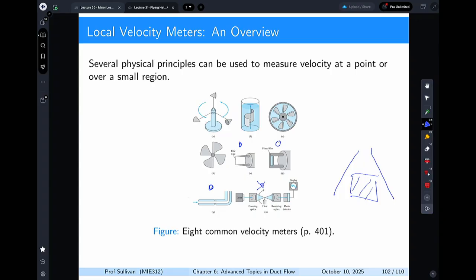The other 2 methods, and I kind of threw that one up there, are PIV, particle image velocimetry, which we've been working on for a number of years, and LDV, which I used back in 2000, and it was great, except to put things in perspective. Hot wire cost me roughly $5,000 to set up, and I can do all of my own software for that, so it's really good. Pitot tube's easy. PIV, we do our own software. Setup cost is about $100,000. We use that to measure flow over airfoils and do things like that.